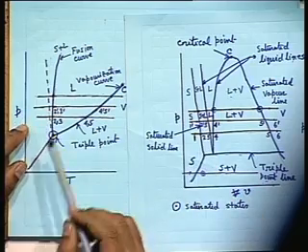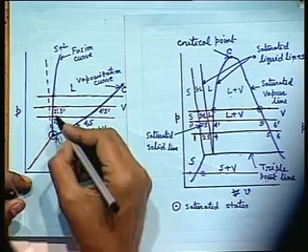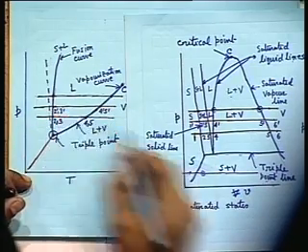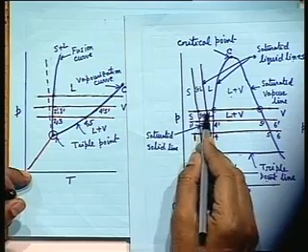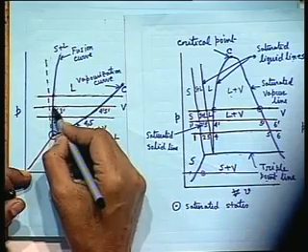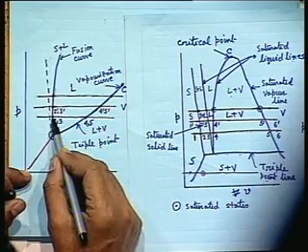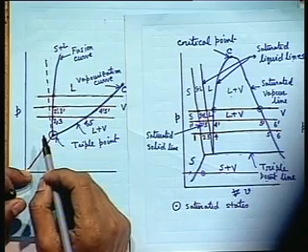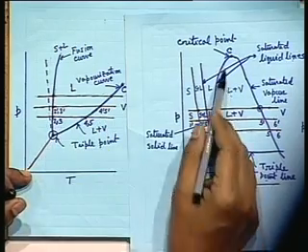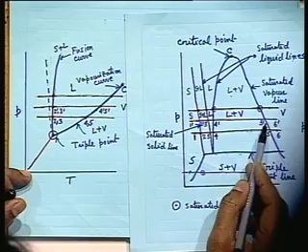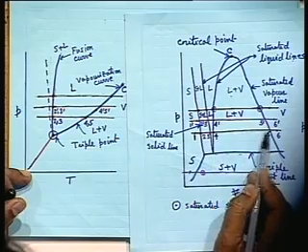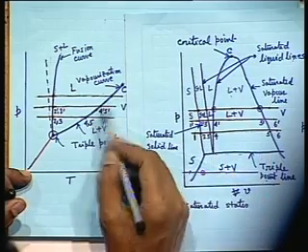But when you do it for the PT plane, then the two saturated states at the extreme of the 2 phases coincide to a point, because they correspond to a single point with pressure and temperature. Similarly for the vaporization curve also, the 4, 5 points, the extreme ends of the 2 saturated points, also coincide.